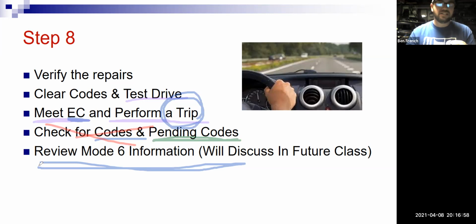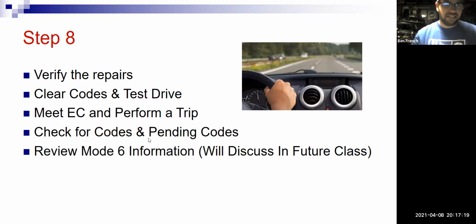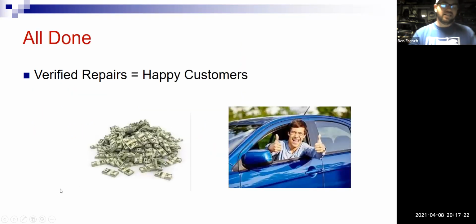If you've done all these things correctly, right? Verified the complaint, pulled the codes, looked at your freeze frame data, recorded that, looked at whether the scan data matches that, done your pinpoint test, done good repairs, and verified those repairs. If you do all that stuff right, guys, at the end of this thing, you end up with a happy customer. And so that's why I say verified repairs equal happy customers, because you can give them the car and you have a good amount of confidence that the check engine light's going to stay off, and everything's going to be good.